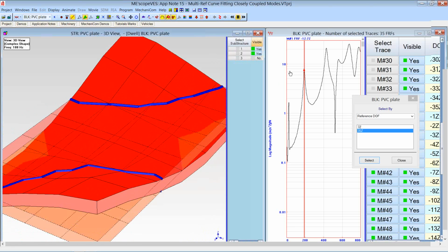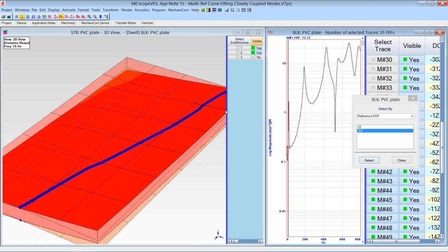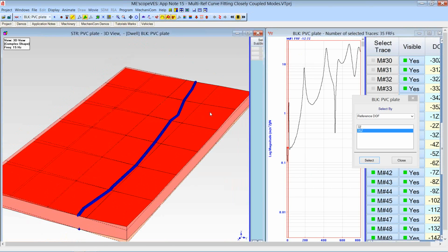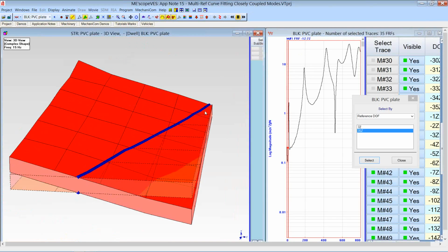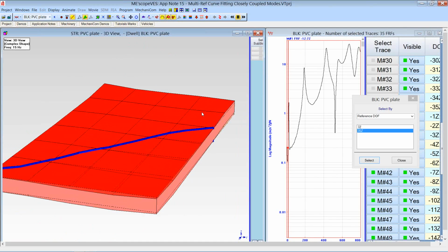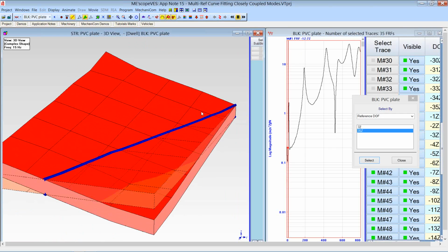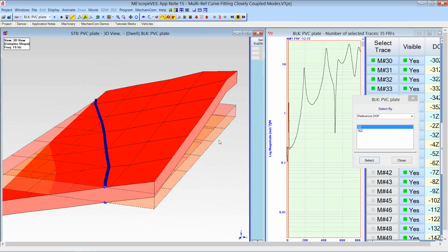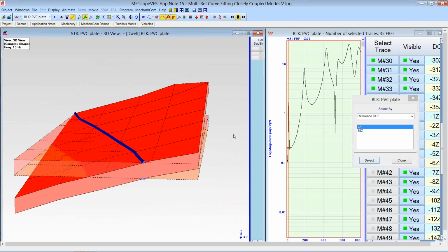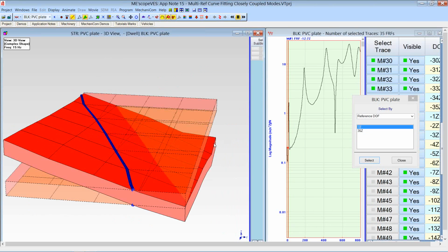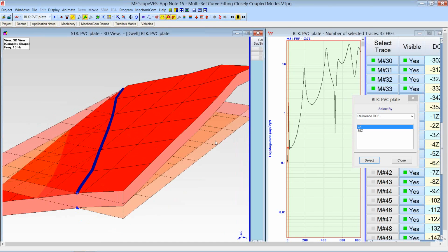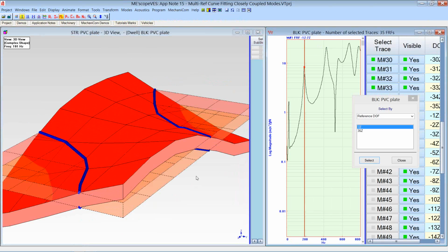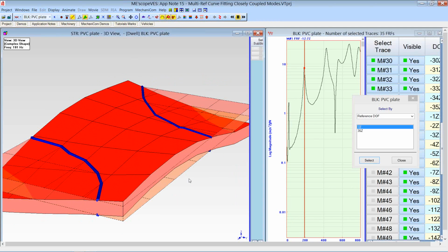Now if I go down to DC, down to low frequencies, I see what I would call rigid body mode. So this is a validation of my data, my 35 points there. And you can see that I got node lines on, so they're kind of rolling around as this thing animates. If I switch to the other reference, I still have basically a rigid body mode. This is just the plate rocking on the foam. I come up here to the first peak though, and what is that?